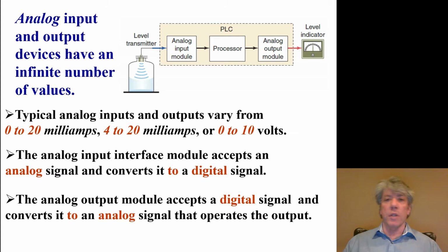So there's some information that's lost because the sensor or the module may not be able to tell the difference between, say, 5.8239 volts and 5.824 volts. It may not have that high of resolution. So there's some round off that occurs, but that's a question that you as an engineer have to answer. How much round off is acceptable? In other words, what's the resolution that I need for measuring the magnitude of this signal? How much pressure variation, for example, or temperature variation do I need to be able to detect? And most of the time, analog to digital converters work with a high enough resolution that it's not really an issue.